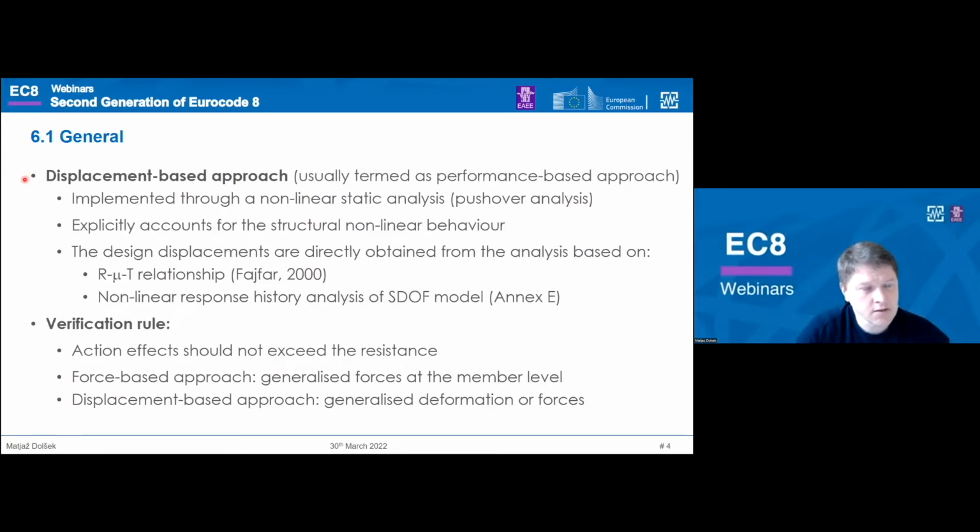Then in the general part, the code also introduced the displacement-based approach. Another term which is used is performance-based approach, but in order to have some analogy with the force-based approach, it is termed displacement-based approach. It's implemented through a nonlinear static analysis, so it is not meant that it can be used based on the response history analysis. The advantage in comparison to the force-based approach is that it explicitly accounts for the structural nonlinear behavior.